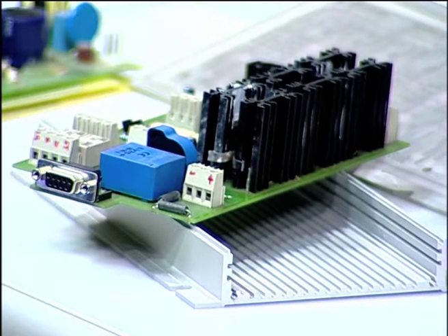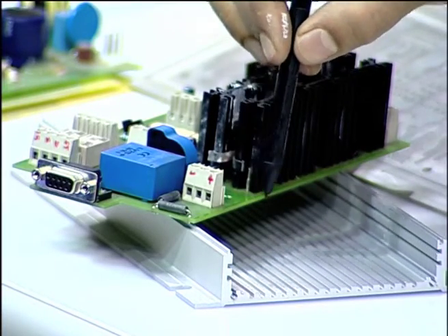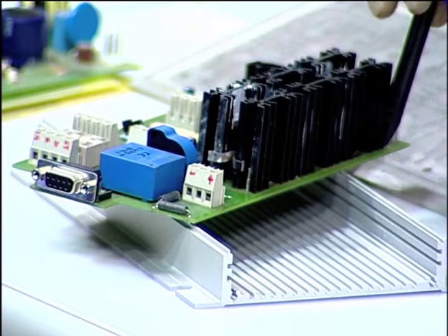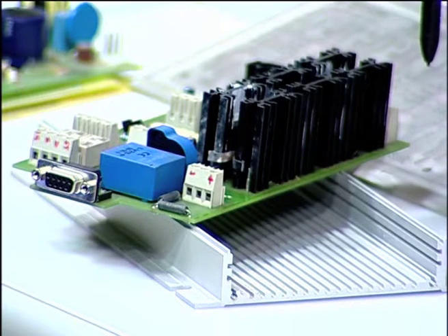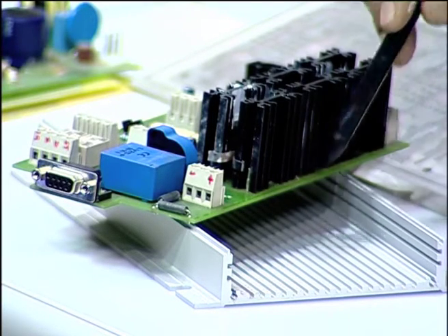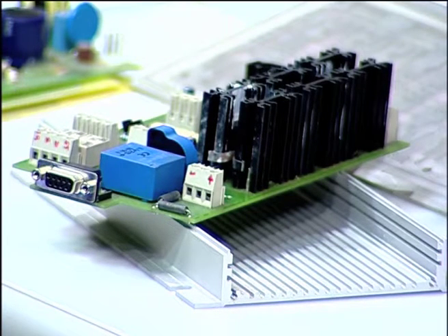That amount of space, about 2 mm, should be clear, should not have any track routing on these edges. At most, if it is not possible to manage, you could have a ground track going on these edges. Otherwise, it is advisable not to have any tracks.